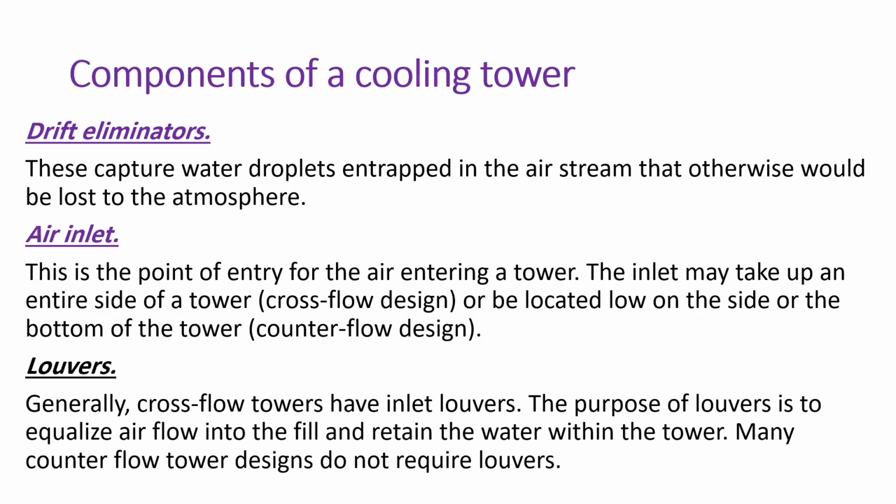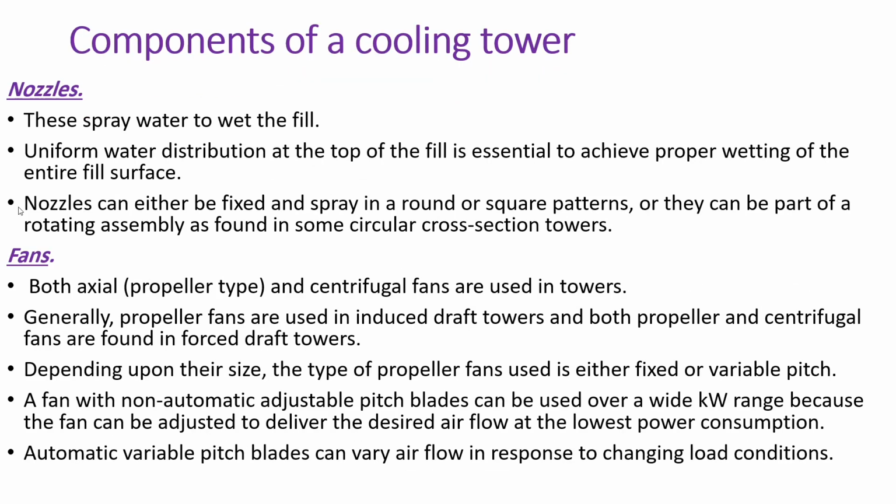The air inlet allows fresh air to enter the tower, and louvers help distribute airflow evenly and help prevent water from splashing outside. These are the main roles of louvers. Nozzles are used to spray water to wet the fill, and also to maintain uniform spraying. Fans move air through the tower.